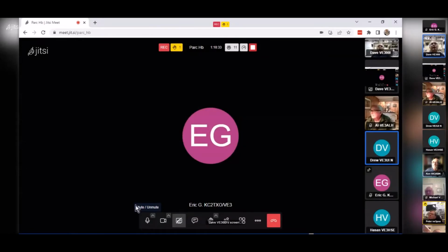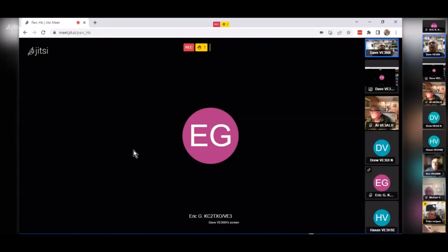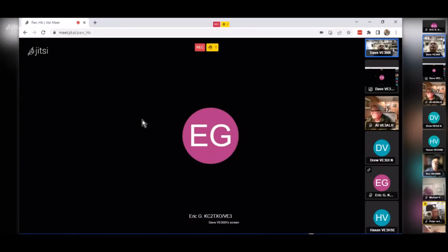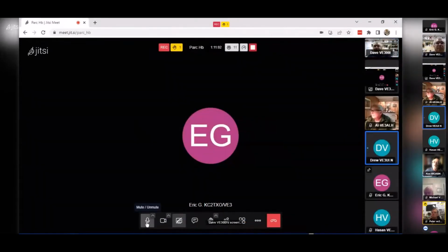No, actually, I found the opposite. If I didn't have that battery at the top, because at first I didn't have it powered with that battery on top, and had a power supply feeding it, the amount of turn the motor would have to make, I don't think it had enough turn. It didn't have enough resolution. Okay, so there wasn't enough resolution in the stepper motor to enact correction.